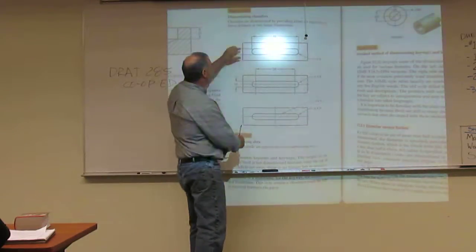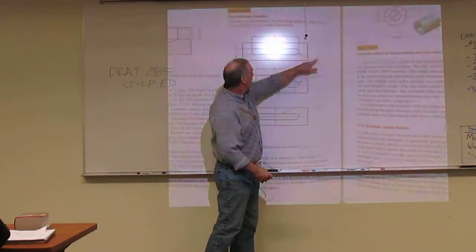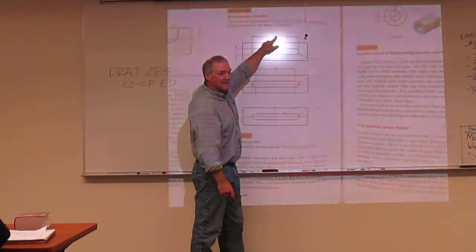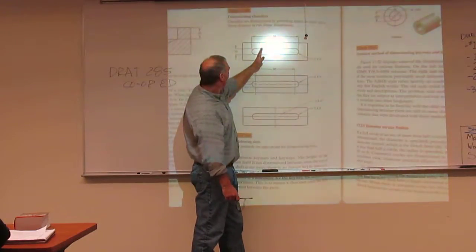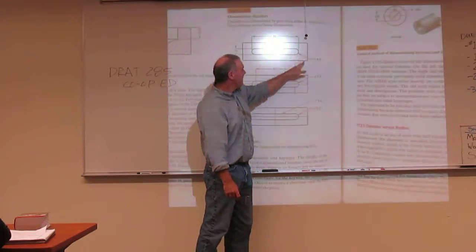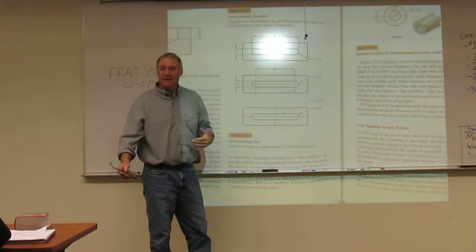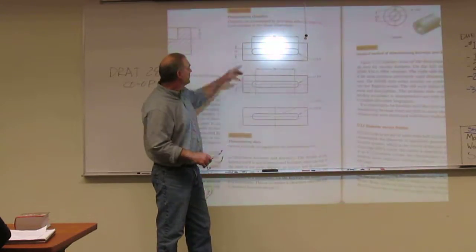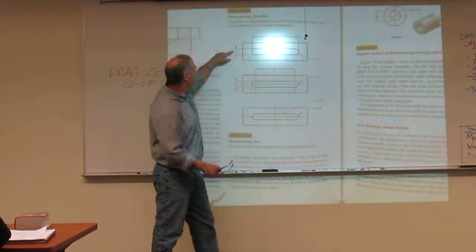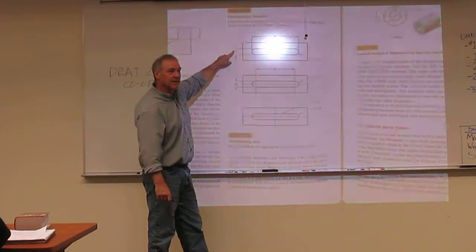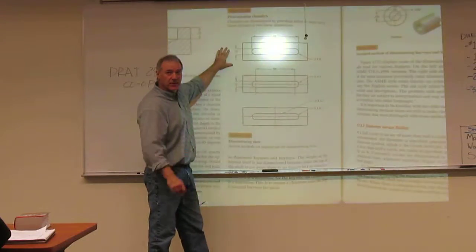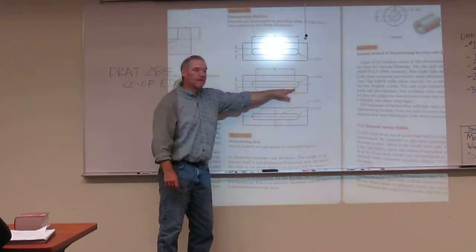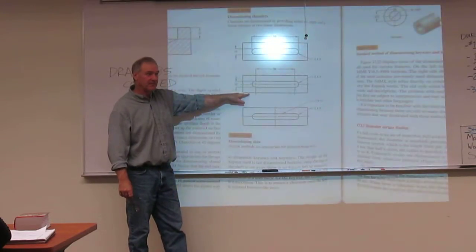So like on this one, where I've got the width of 10, I've got the radius, but then I've also got this length here. Well, I don't need that whole length, because I would do it from center to center, and then 1 radius instead of both of them, then you would be done. Now on this one, they give you too many of them. The radius here is double dimensioned with the width, so normally we would take one of those 2 out. This is really probably the one that's used the most, the center one here.